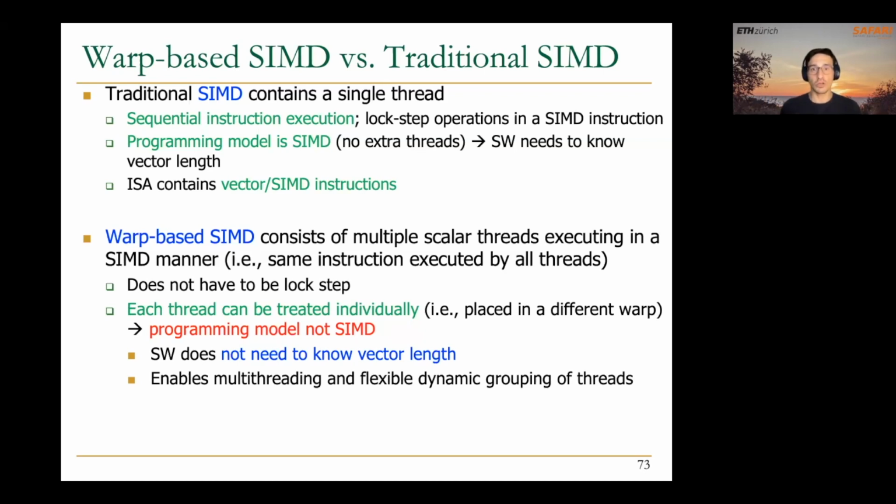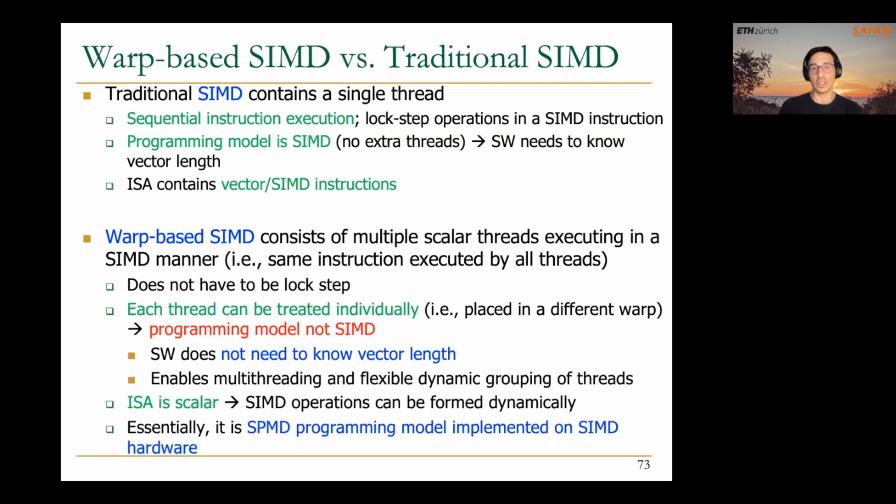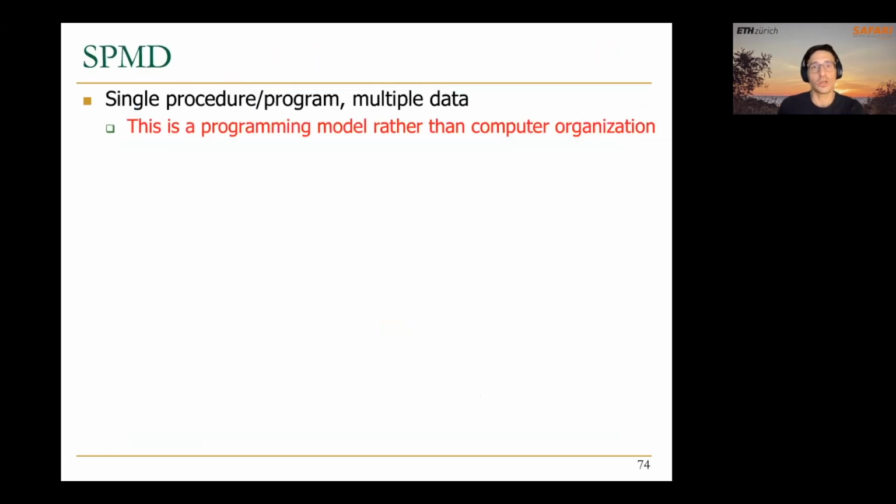Why is that? Because the hardware will be better used and the execution will be more productive. We will achieve higher computing throughput when we take advantage of the whole warp and use all available execution units. But if needed, and because we are using a scalar ISA, it's possible to make threads diverge. And in order to support that, the SIMD hardware has vector masks, as we know.